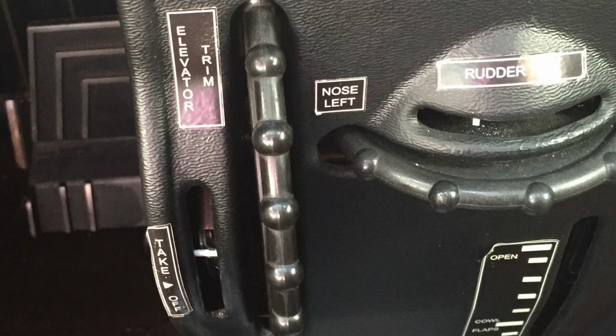but you can trim the rudder left and right. And it's really nice on takeoff because some people like to adjust the rudder just slightly on departure like you would other trim, so you don't have to work as hard with your foot on the rudder pedal on departure, because the tendency is greater with the high performance airplane.